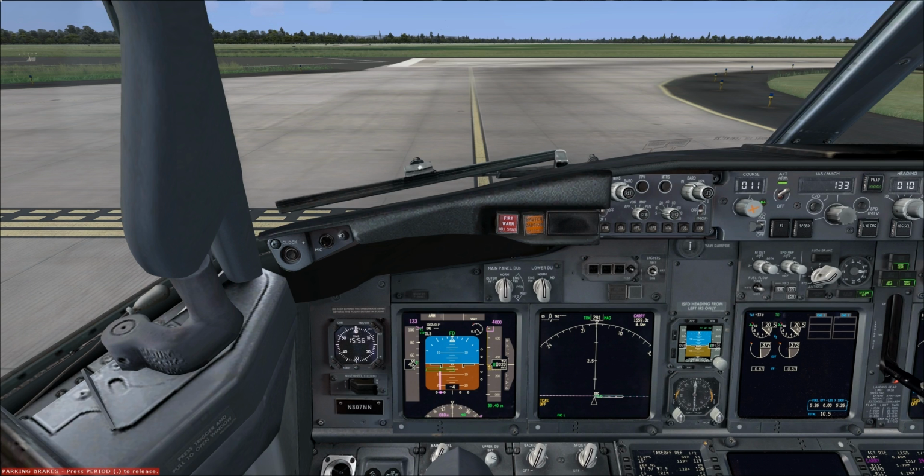If the microburst occurs in front of you on takeoff, the indicated airspeed would show an increase, of course, essentially increasing faster than your ground speed. So if you see a rapid jump in airspeed and your ground speed isn't showing that same jump, then obviously you have an increase in headwind.